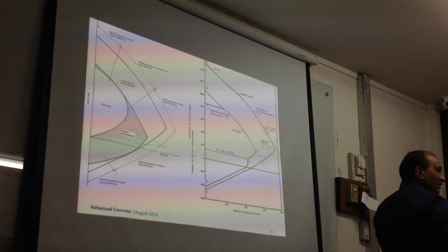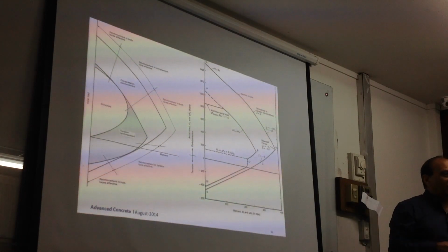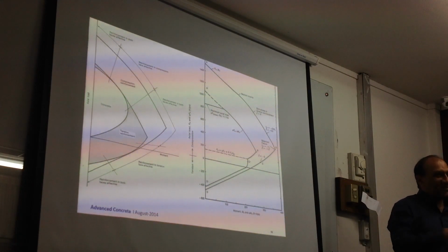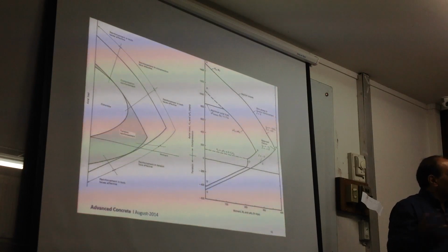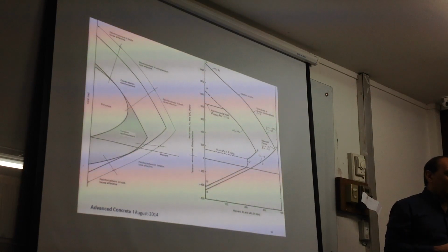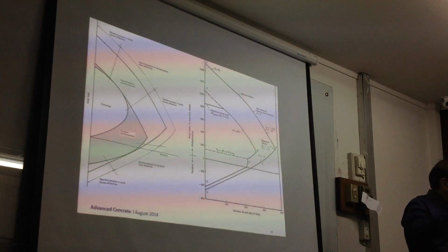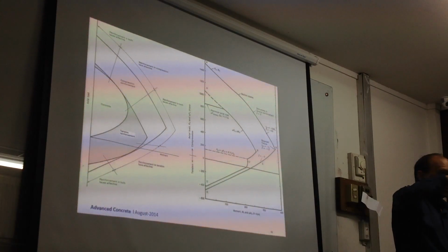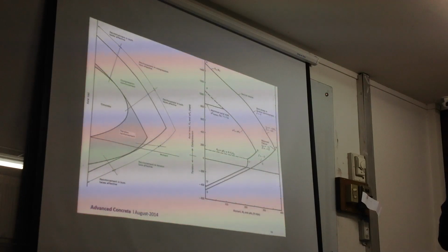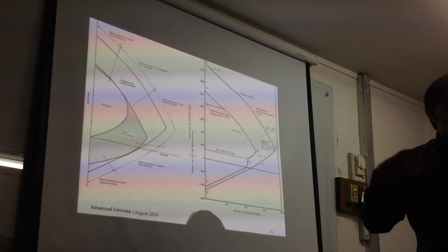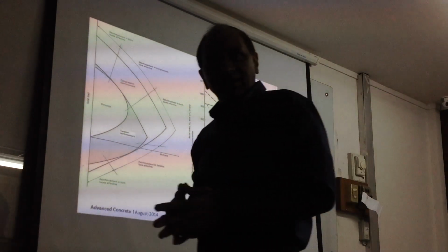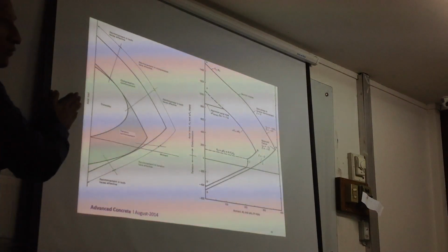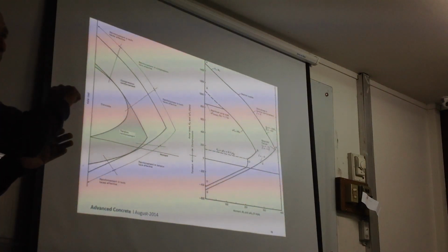But the problem is that there are 10,000 or 5,000 combinations. Some cases compression, some tension. So we need to know this for all of the cases, which is too much. So we calculate the maximum. That's why these points are very important. We need to know where we are so we can check for the corresponding splice length, corresponding crack width and many things. So this curve has a lot of rich information if we know how to use it.